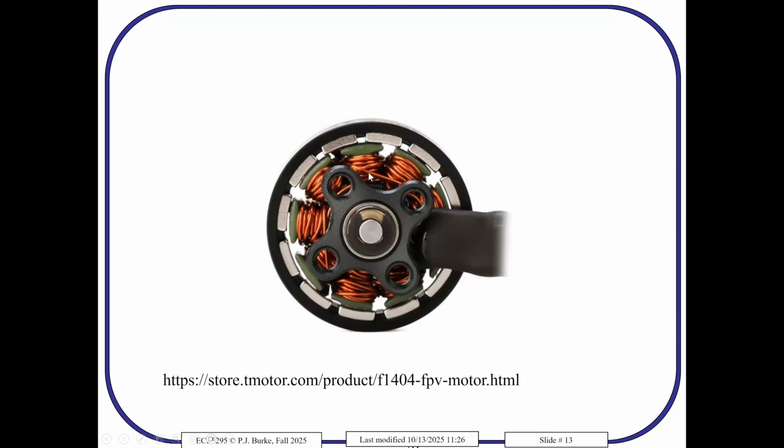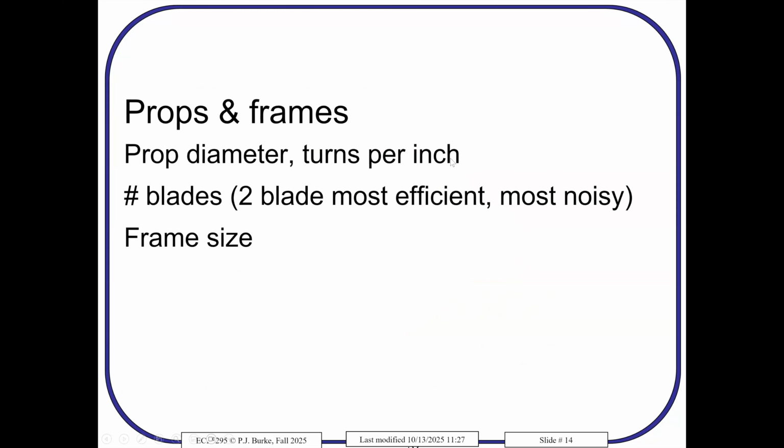copper. By the way, be very careful when you're using these motors because they're exposed. There's no cover. And if you have a little piece of metal, it'll get sucked into there, because the magnets are very, very strong, and then it'll mess up the motor. So if you clip off one of those 0.1 inch DuPont pins and you're within an inch of this motor, it's gonna suck it in. You can go in there and get it out manually with the tweezers, but be careful. Don't allow metal things that are loose near it. Little screws might get in there, so be careful.